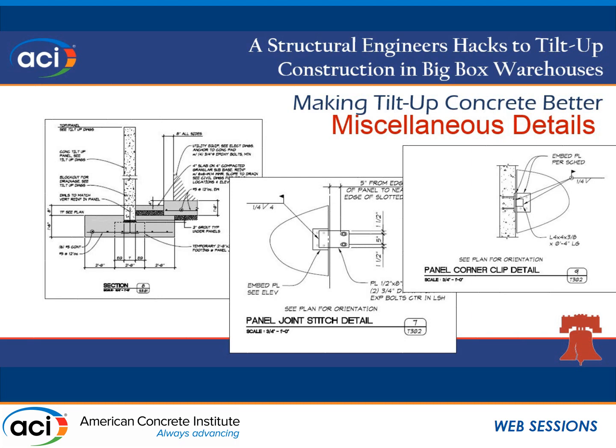on the panel joint connections, right? It's not an expansion problem, it's a shrinkage problem with the thermal, right? The metal is as hot as it's going to be, and then it shrinks back when you weld the far side. So if you can keep your welding area to a minimum, it helps really cut down on the thermal. But yeah, I don't see too many cracks there.